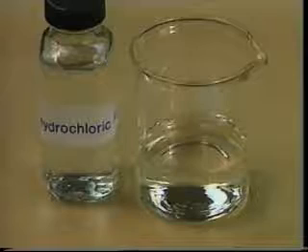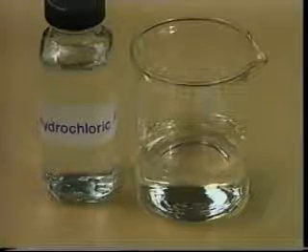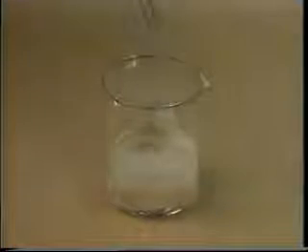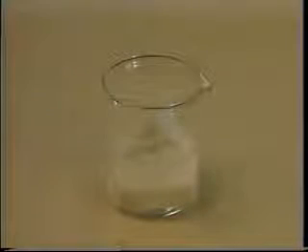There are several types of acid used in oil field applications. By far the most common are the inorganic acids, hydrochloric and hydrofluoric. Organic acids, such as acetic and formic, are used occasionally. The most commonly used acid is hydrochloric. Its popularity is due to its ability to dissolve large volumes of carbonate without forming damaging precipitates.